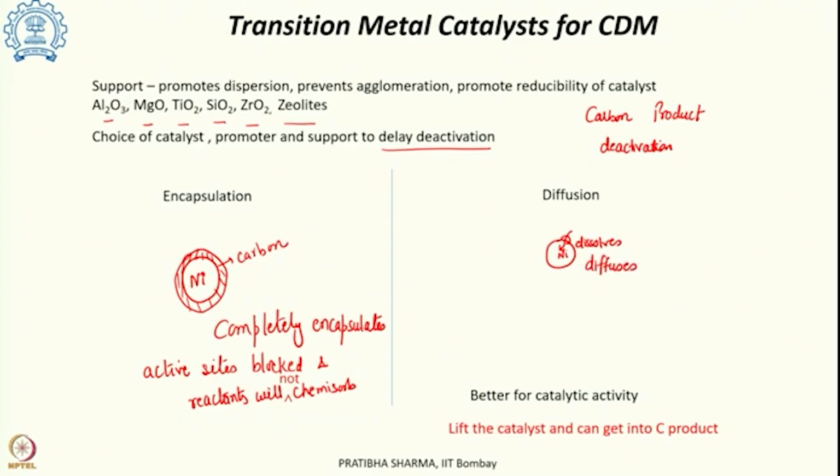Herein much of the surface area is still left out, wherein there is no carbon deposit. So, this still remains active where the carbon deposition has not occurred. So, if there are free surface or active sites available even after carbon deposition, which diffuses inside, then the catalyst deactivation gets delayed.